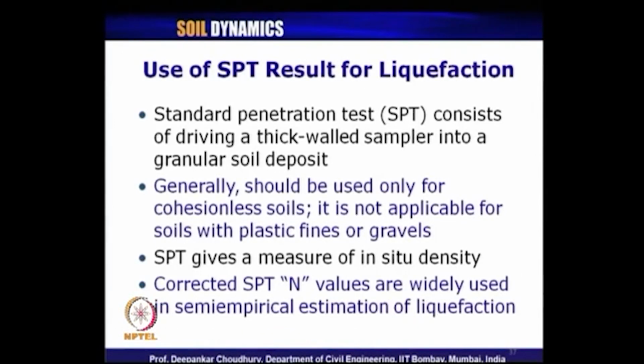Now, how to use the standard penetration test results for the estimation of liquefaction? Standard penetration test you all know from any basic course of soil mechanics, so I am just quickly going through it. The standard penetration test consists of driving a thick walled sampler into a granular soil deposit mostly. Generally it should be used only for cohesionless soil, but it is used for soil with plastic fines also, that is, for C5 soil also.